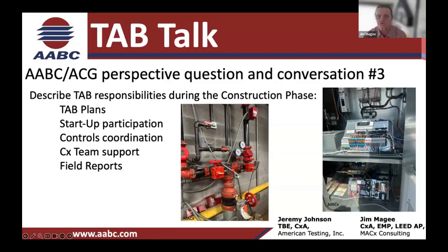When I commission hydronic systems, Jeremy, it's hard to imagine, but the vast majority of mechanical contractors do not establish pressurization control in their hydronic systems. They don't get the right expansion tank pressure. They don't put things on the low point of suction side. It's crazy, and sometimes guys balance them that way. There's 3 F's of hydronic systems. It's filled, flush, free of air. Filled and free of air kind of could be the same thing construed, but the bottom line is getting these systems filled correctly, right?